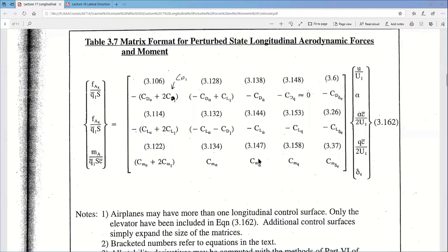Totally, yeah, the word lag means falling behind, right? If you're lagging somebody in a race, you're a time delta t behind them. So it's the delta t time it takes for the downwash change at the wing to get to the tail. So now we've done this column.